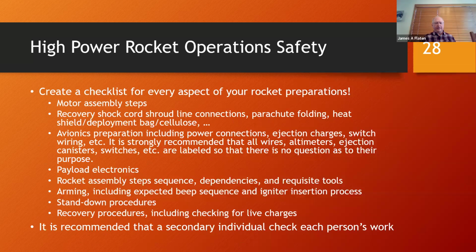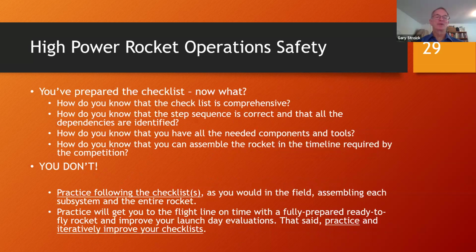That last point about including checking for live charges is very important. When the rocket is recovered, you need to understand whether or not there is still anything explosive in the rocket. And if there is, you need to have a well-documented procedure to deal with that. We don't want someone getting hurt when they're out there trying to recover the rocket. So that needs to be checked.